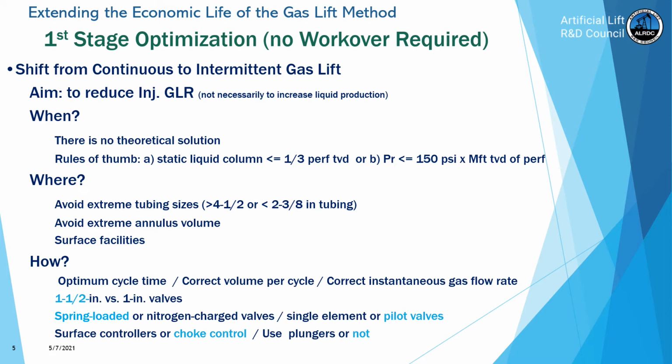But here, if we are going to lower the pressure, then we have to make sure that at that new lower opening pressure, the delta P across the valve is going to be large enough in order for the liquid slug velocity to be high.